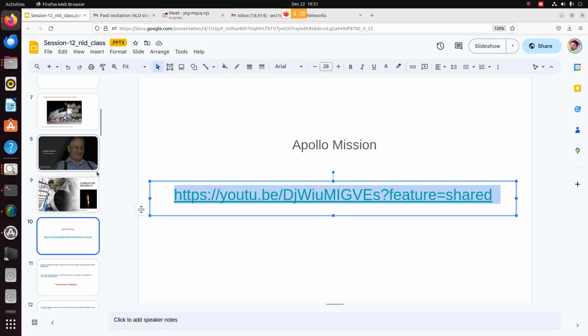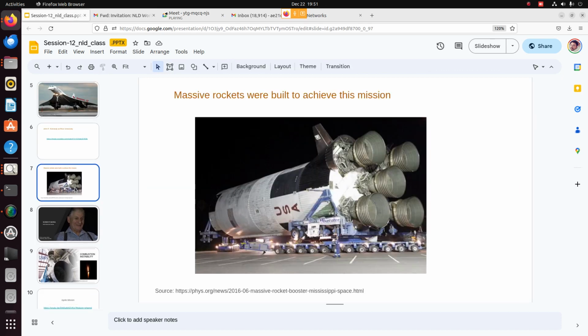So that's how they solved that issue on the combustion instability problem. So the nonlinear dynamics we have learned, we can use as a precursor to the upcoming instability, or use them to mitigate it, as people have shown mitigation strategies, and people have also shown different ways to study the mechanism or the qualitative dynamics which different combustors exhibit. These are very good examples to study the different bifurcations that are happening within a system. Out of those, the complex networks method was taught by Shruti over the last sessions, and there are many other measures like synchronization and recurrence quantification measures, which were key to address these different oscillation states.